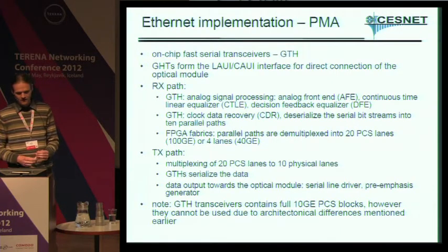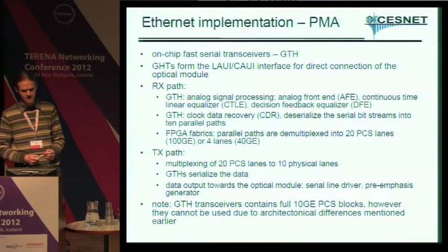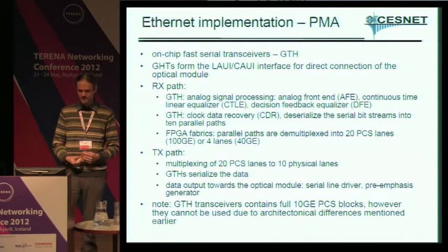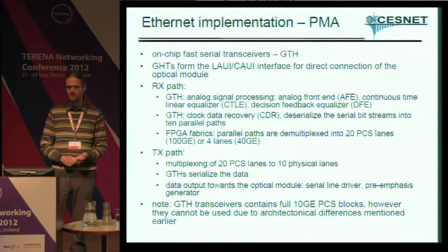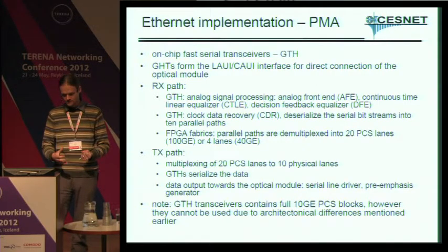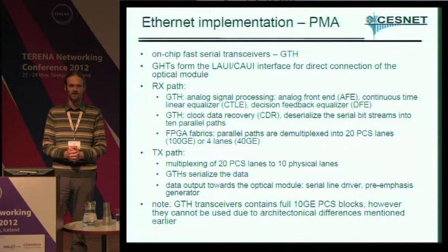The note here says that GTH transceivers are so advanced that they do have a complete implementation of 10G Ethernet in them. However, we have to bypass almost everything in those transceivers because 100G is not 10 times 10G.